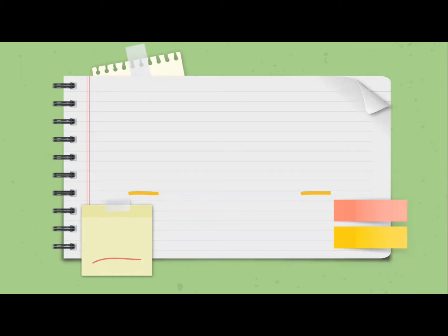And lastly, we have here the importance or application. Stability is the tendency of a floating object rolling from side to side to return to upright position. By the use of this, the principle of flotation explains how ships float. The principle of flotation states that a floating object displaces a weight of liquid equal to its own weight.